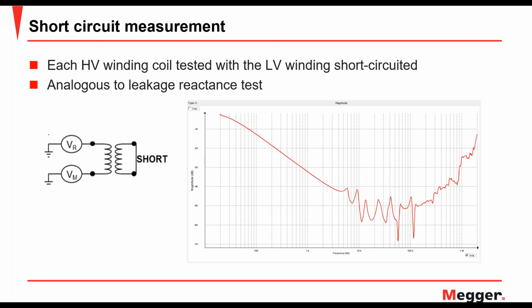Now that equivalent three-phase impedance is supposed to be very close to the percentage short circuit impedance given on the nameplate of the transformer. The IEEE field testing guide mentions a limit of 3%, so it should be within plus minus 3%.